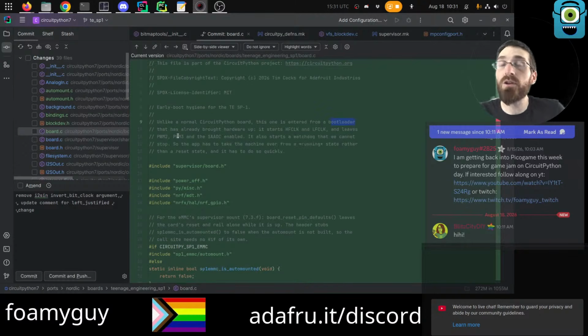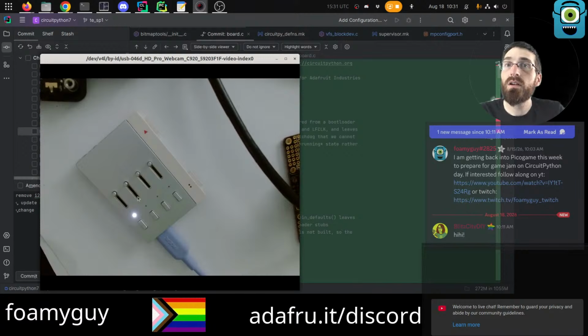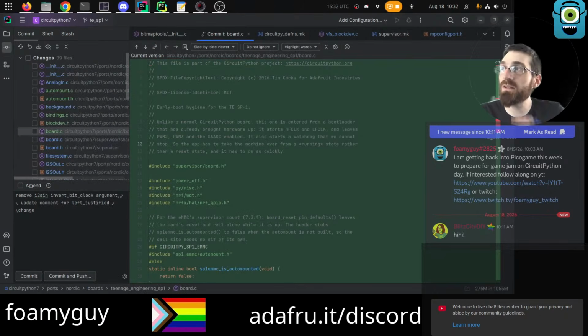So how this ties back to the PWMs and stuff here, those buttons are using a resistor ladder. So they are not just plain old digital in out, one button to one pin jobbies. Instead, there's a single pin that reads a bunch of buttons, and there's a resistor ladder. So when the buttons are pressed, it makes a different resistance.